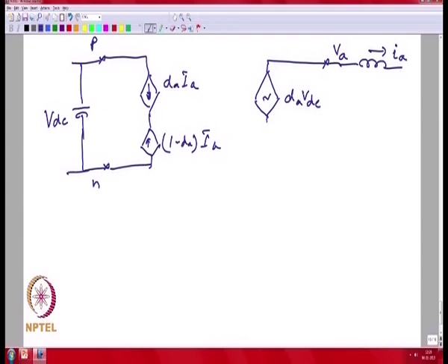If you look at the voltage d_A, it is actually with respect to N, and here what you end up with in this model is that this particular point is also linked to the same reference. So, the bottom part of this model, you have a current source which is going into a short circuit. So, you find that this particular path is redundant.